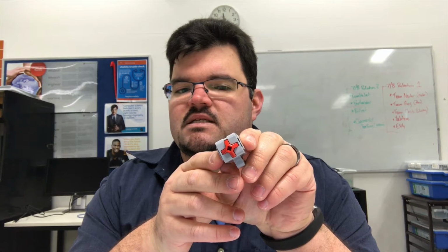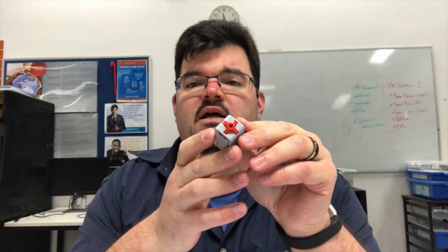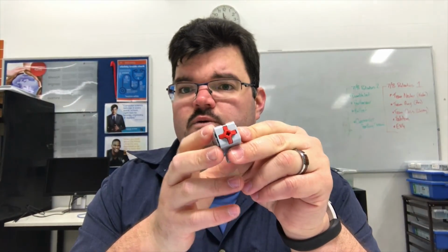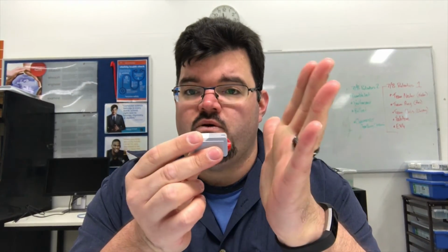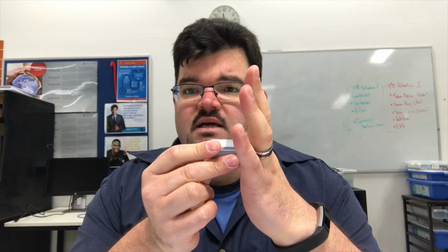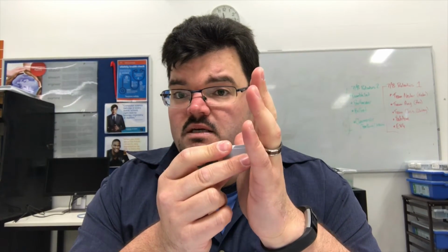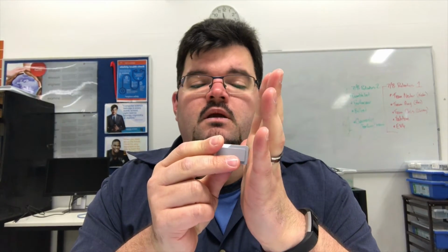This is a sensor with only a couple of options: not touched, touched or pressed, and then released. Those are the three different kinds of settings that it can detect. One of the common things that we use touch sensors for is whether or not your robot is touching something. So if it's come into contact and it's detected as being pressed, your robot can use that as a way to make sure it turns its motors off. Okay, so touch sensor on, off. That's the basic touch sensor.